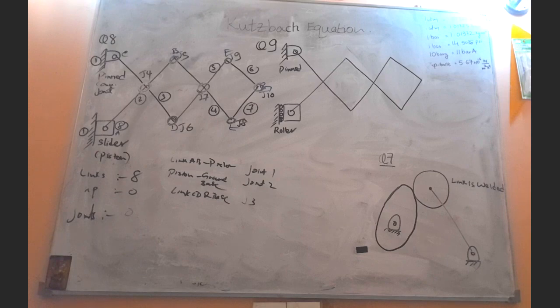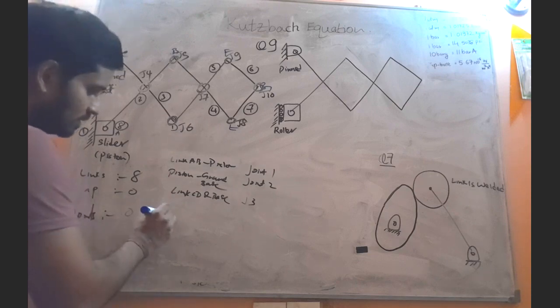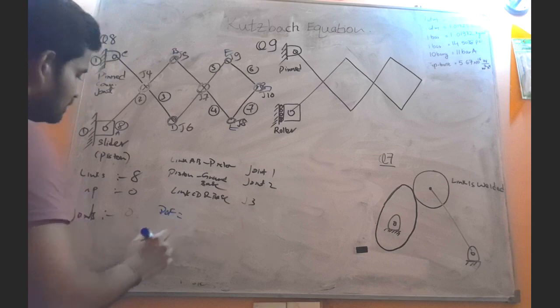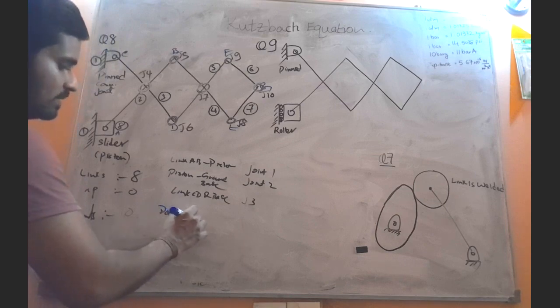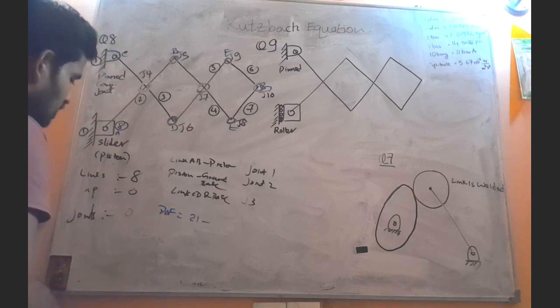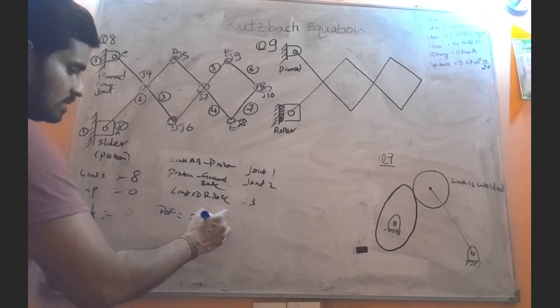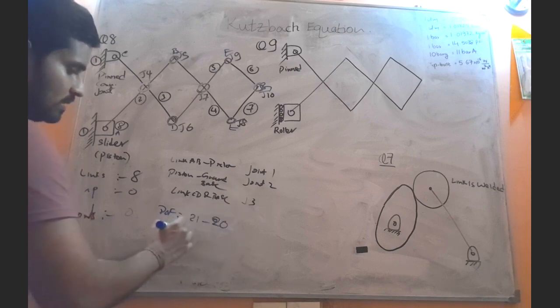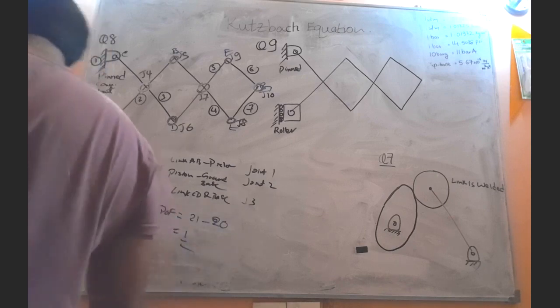So now let's focus on the equation. The degree of freedom equation: 3 times the number of links minus 1, minus twice the number of joints, twice 10 is 20. So the degree of freedom is...